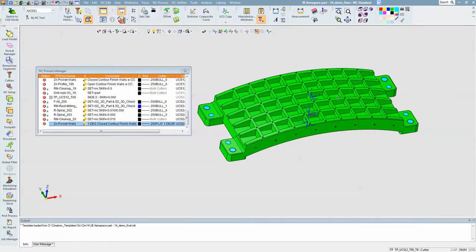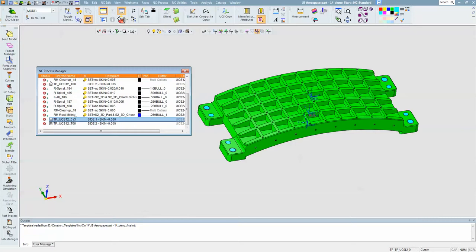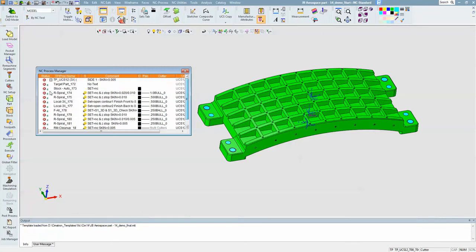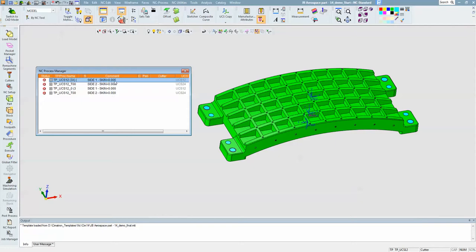It could also be all 4 sides, or whatever you want. And each toolpath folder represents machining to within, say, 5 or 10 thousandths on the top side, and then 5 or 10 thousandths on side 2, and then going back and machining side 1 to 0 and machining side 2 to 0.